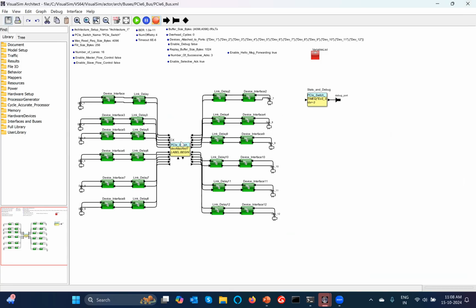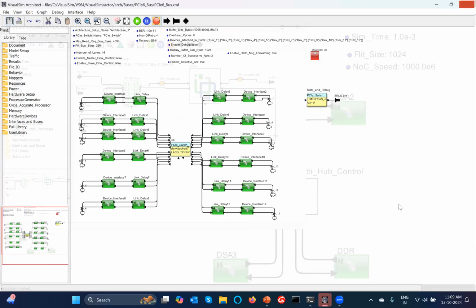Also notice these are what we call our IP builder blocks. We're not just building the PCIe from scratch, but rather we build building blocks that can be easily reused for creating other blocks. For example, the building blocks here were reused to create CXL, PCIe, UCIe, all of those. We're using a single set of building blocks that was slightly modified or parameter changed to make that implementation.